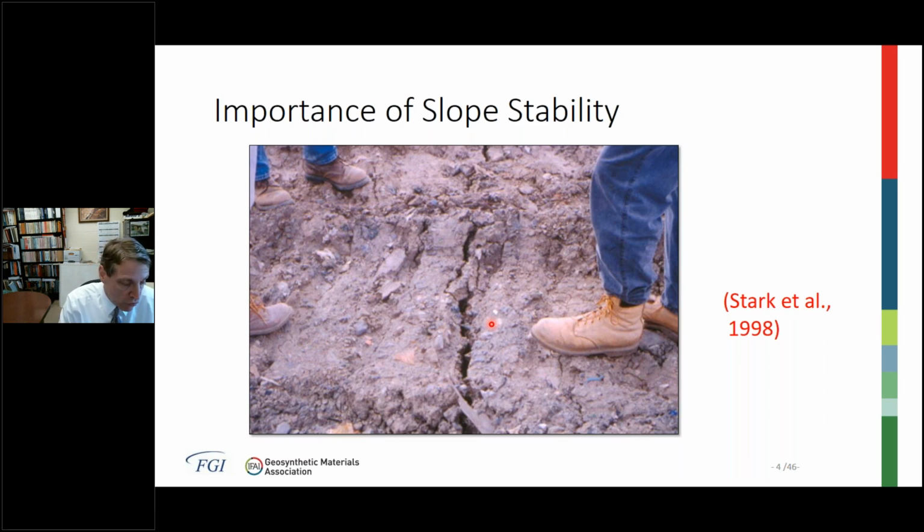Second thing about a tension crack is they will usually reappear in the same location in a short period of time. So if you cover it up, and that's not highly advisable, I'll talk about what to do with them in a minute, but if you covered it up and it's a tension crack, it'll reappear in that area in a short period of time. Whereas a settlement crack, if you cover it up, generally it won't reappear there in a short period of time because it's undergone some settlement and some other area will probably crack before that area cracks.